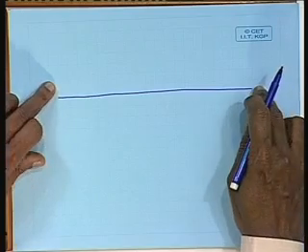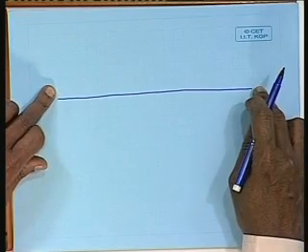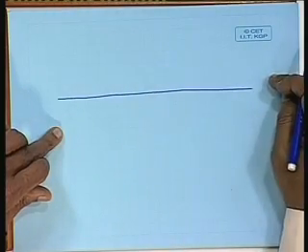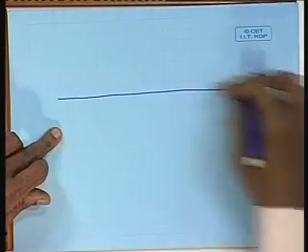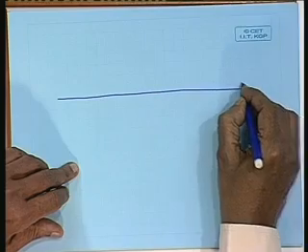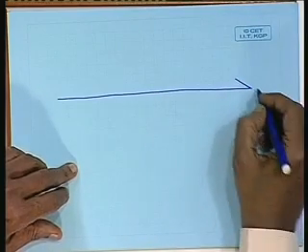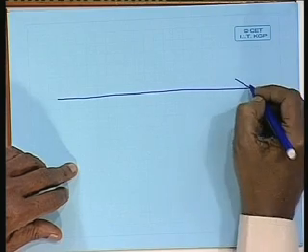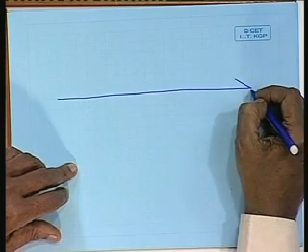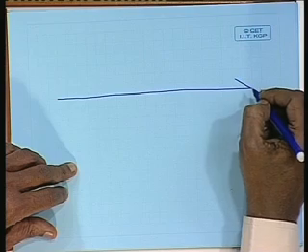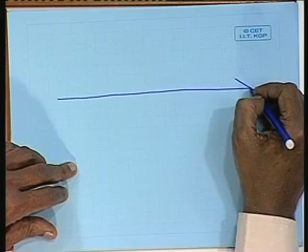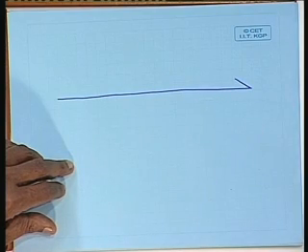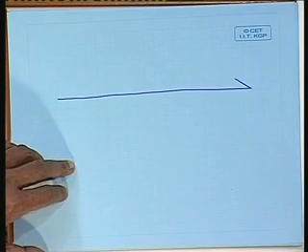If you look at the waterline, if this was a flat plate, you will not get any wave making resistance, because the slope of the waterline here is 0. The water comes straight and goes past. When I am putting something here like this, certainly the water cannot go past here anymore. So, it has to go like this. Therefore, there is a pressure point. The pressure point is coming primarily because of the generation of waterline slope, that is, the gradient of the waterline. Do you understand this? Okay.